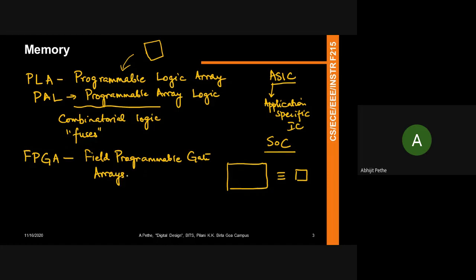These are chips which are normally used when you're thinking of a specific product, right? Suppose you want to design a next generation gaming chip, which has very complicated algorithms that you're implementing on silicon. Once you design your algorithms and your architecture, the normal cycle is that you put everything on silicon, run a test chip, and send it to your foundry. The foundry sends back a chip after 6 to 8 months. You test it, you reassess your design. By then your customer might have defined certain new requirements. You put them again into a test chip.